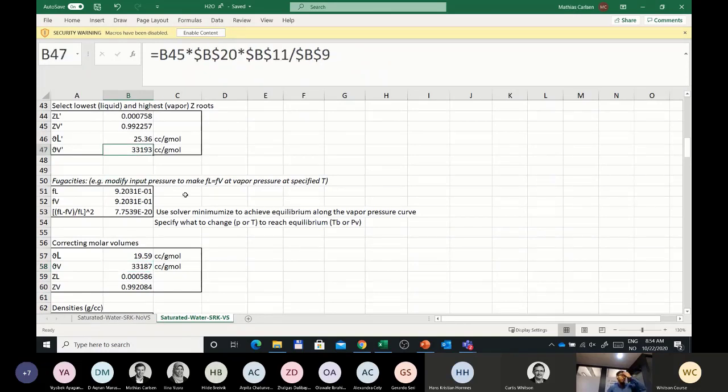We also know that the vapor phase densities are usually okay without the volume shift, unless we go to very near critical conditions or very high pressure and temperature, where vapors have very similar density to the liquid phase. There the magnitude of the vapor volume will be smaller, and the correction will have more impact on correcting the densities or the molar volumes.